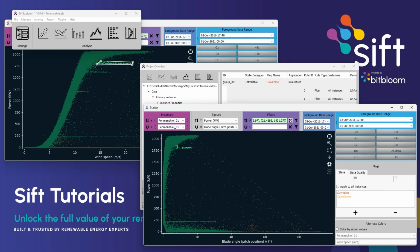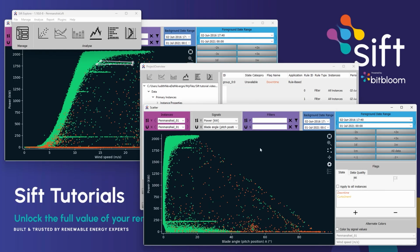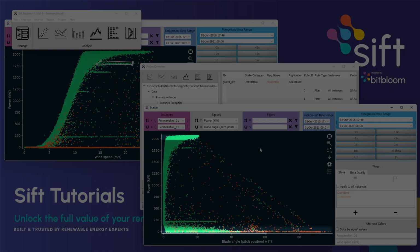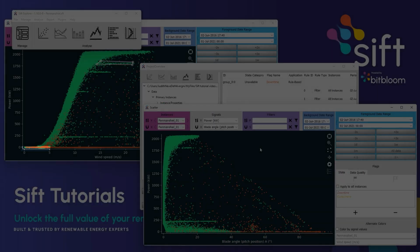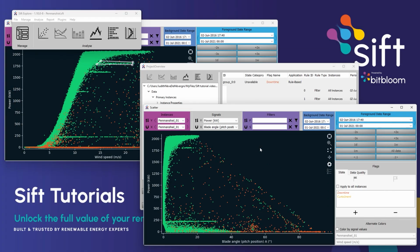This rule will categorize all horizontal lines on the power versus pitch curve as curtailments. However, some are normal operation. The search rule filter string can be used to limit the search. Points at zero power can be a mix of normal operation at low wind speeds and curtailment to zero power at high wind speeds. To differentiate between the two, we use generator speed.